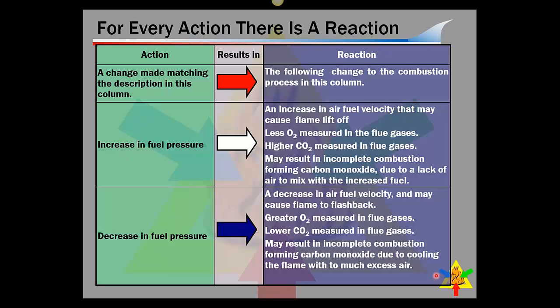Okay? So that's what those numbers are telling you. And you can affect your O2 and your excess air simply by changing your fuel. Can anyone think of other ways that you can affect the amount of air that goes into the combustion process on an appliance?